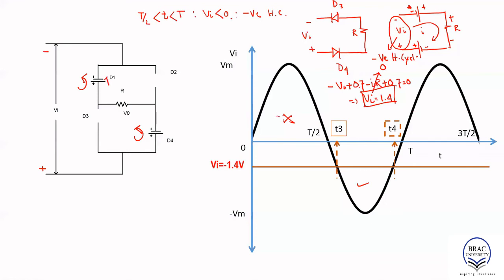So this is the orientation of the diode. So in that case, we know that below the line the diode is on. For the range of voltage below the transition state line, the diode is on, and the range of voltage above the line is the off state. So we found out the range, the boundary at which transition between on and off occurs.